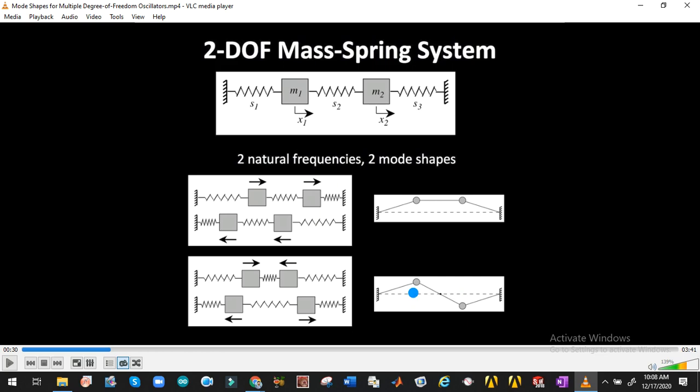So there are certain ways where we can decrease the vibration amplitude of a particular mode. For example, we can provide a stiffness element at a particular point. We may provide a damping element within the system at a particular point.